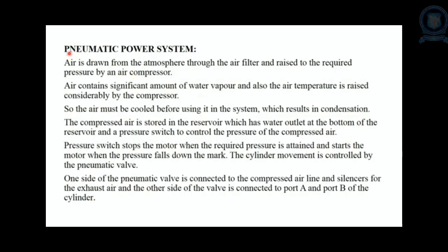Then the pneumatic power system, the components are almost the same. That is, air is drawn from the atmosphere through the air filter and raised to the required pressure by an air compressor. Air contains a significant amount of water vapor and also the air temperature is raised considerably by the compressor. So the air must be cooled before using it in the system, which results in condensation.